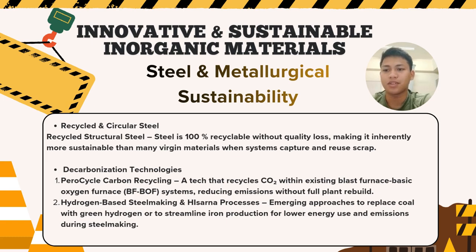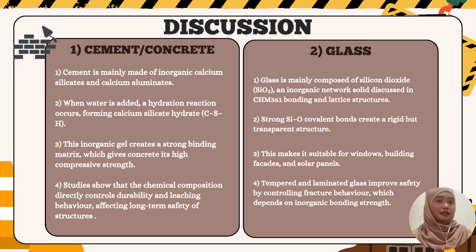The second one is decarbonization technologies. The first point is Pyrocycle carbon recycling, a technology that recycles CO2 within existing blast furnace and basic oxygen furnace systems, reducing emissions without a full plant rebuild. The second one is hydrogen-based steelmaking and HIsarna processes. These are emerging approaches to replace coal with green hydrogen or to streamline iron production for lower energy use and emissions during steelmaking.